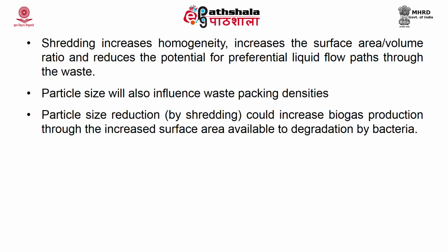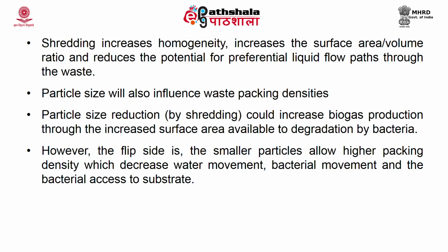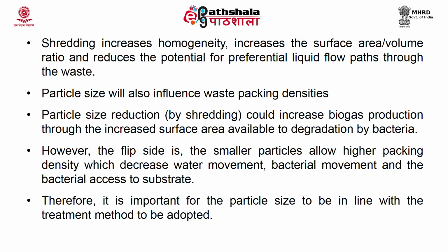Particle size reduction, that is by shredding, could increase the biogas production through the increased surface area available for degradation by bacteria. On the other side, this can be a disadvantage also. The flip side of this method is, smaller the particle, higher will be the packing density, which will decrease the water movement and the bacterial movement and will decrease the accessibility of the substrate to the bacteria. Hence, the particle size is very important and it should always be in line with the treatment method to be adopted. If you are preferring biodegradation or composting, then the particle size should not be very small. As mentioned, it will decrease the accessibility of the substrate to bacteria, thereby reducing the performance.